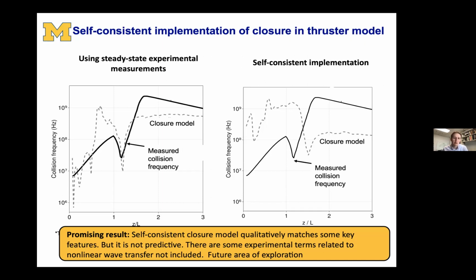You can get the ion acceleration correct. You'll get the thrust generation correct. You'll get the efficiency of the thruster correct. The idea is actually knowing this profile is not sufficient. Yeah, that's right. It is not sufficient just to impose that profile. If you want to make your code match experiments, then if you implement this black curve spatially in the code, which in a sense is some sort of closure, you will directly match experimental measurements, but it's not predictive. And that's the key distinction there, because this profile changes depending on operating condition. It'll move location or amplitude or even shape to a certain extent.